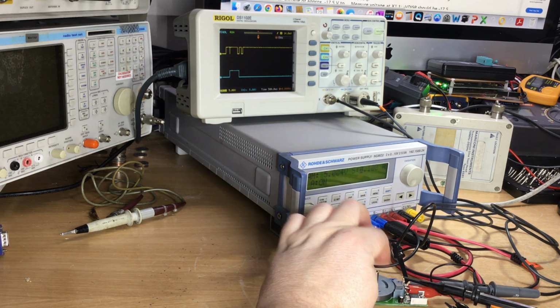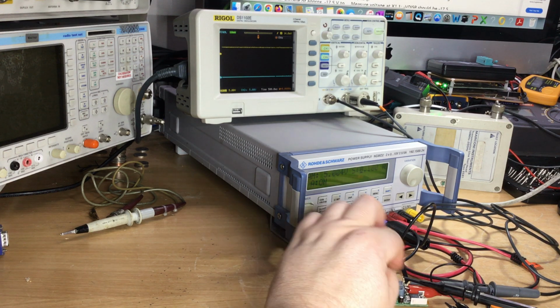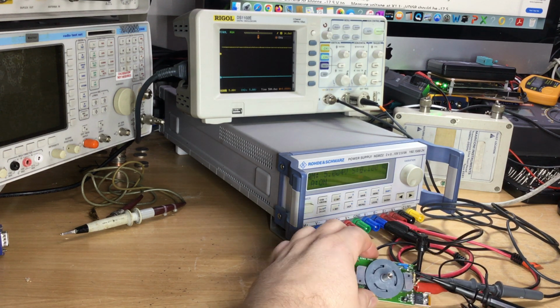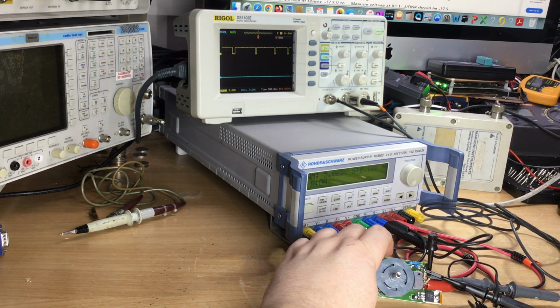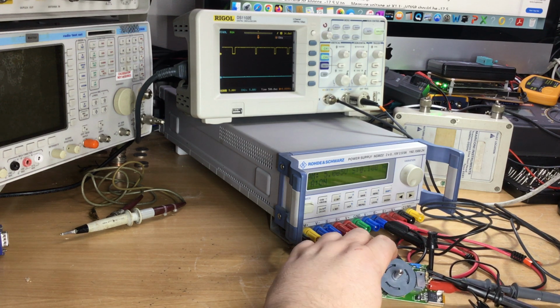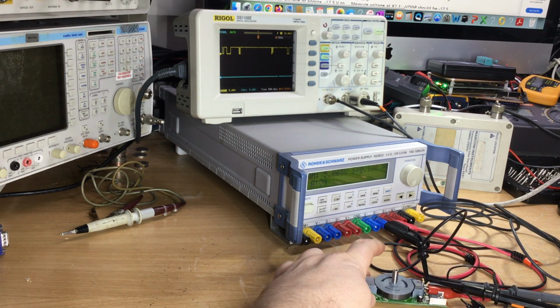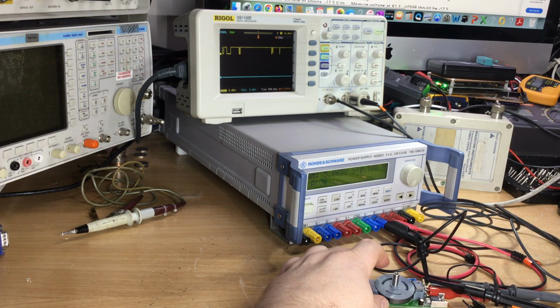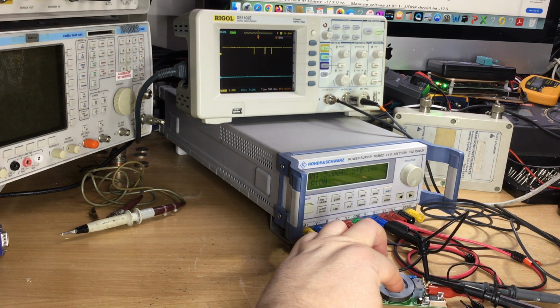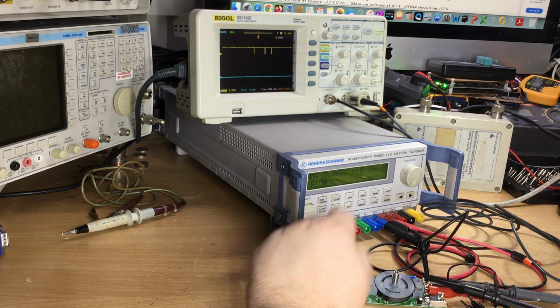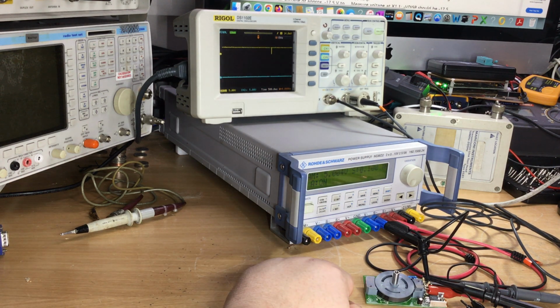Also, we'll check for dry joints as well, and soldering on the devices. There's a couple of through holes as well, I've noticed, on the PCB in places, which has connected the signal in wires to the actual pins on the socket down there. So it could be some through hole as well that might need soldering, but just disturbing the board, just touching the wheel without turning the wheel, causes a pulse train to develop, as you can see there. So very strange, very strange. Right, let's strip it down now and try and clean it up.